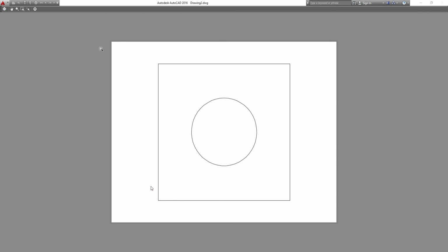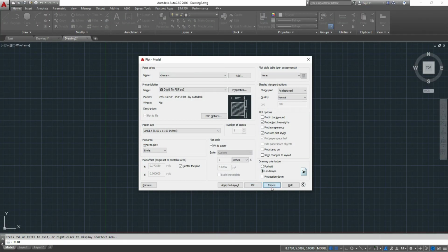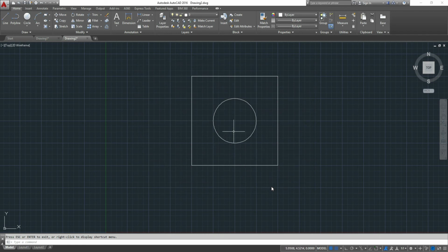I wanted to show you how to set up the limits and what role they play in aligning your grid and printing, and how to set up your environment using the F3 or D settings command, the zoom shortcut, line shortcut, circle shortcut, and erase shortcut, basically Z, L, C, and E. That's all I basically want to show you in this video.